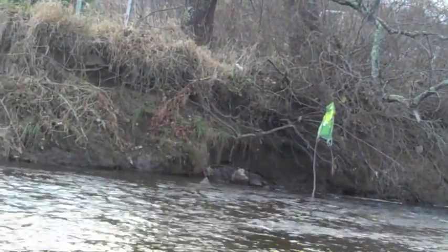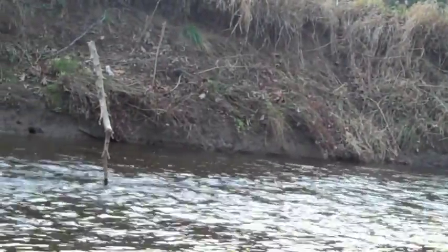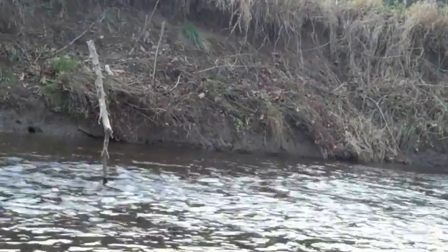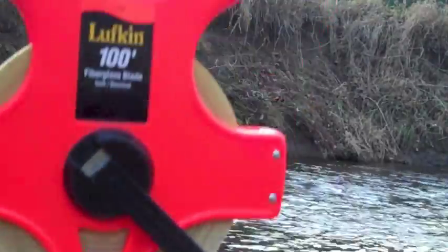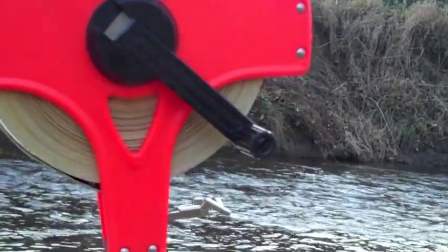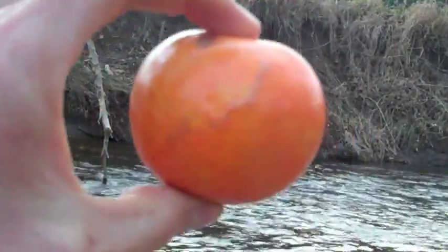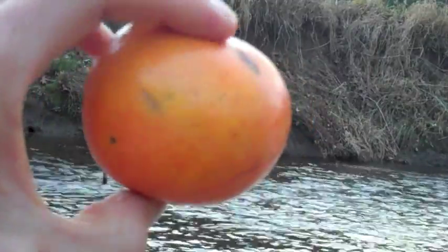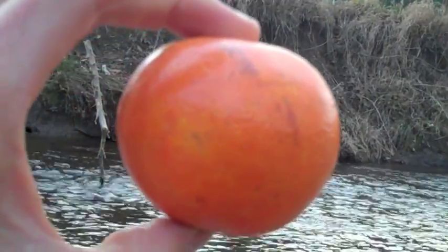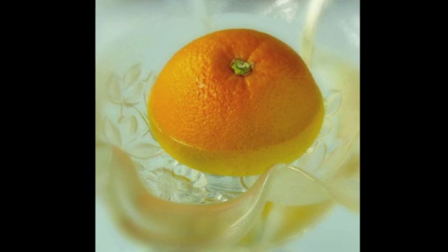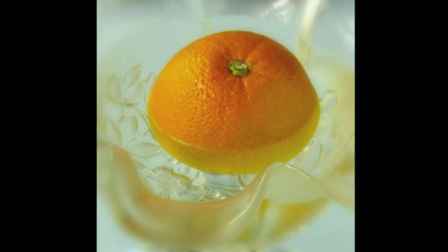In order to carry out the float method, you must first measure off an upper and a lower part of the stream to run your float method on. This can be done with your average everyday tape measure or any measuring device such as this one shown here. We will also be using a stopwatch, which I'll show a little later. And to act as a float, we will be using an orange. Why an orange, you ask? Oranges neither float nor sink, making them an excellent flotation device for our purposes.